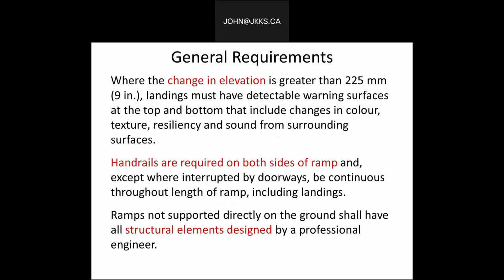Again, some of the general requirements, when we talk about it, getting away from the building code but still inferring that it's going to be close to the building code. Where the change in elevation is greater than 9 inches, landings must have detectable warning surfaces at the top and bottom, including a change in color, texture, resiliency, and sound from surrounding surfaces.